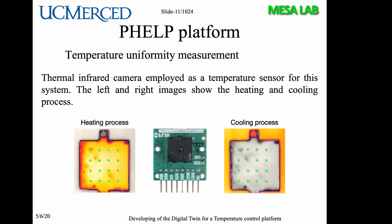Here is an image in the center of the camera, in the left side, the heating process. And we use 16 green dots to represent the position of each Peltier. And this is the value of temperature that we are measured in our system to control the temperature. So using this surface of aluminum, we create the interaction between all the Peltier, and with this interaction, the dynamic can be represented by a MIMO system.